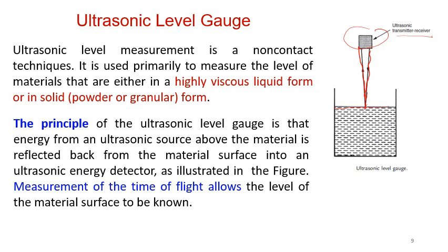The simple way of analysis is just to measure the time taken by the signal from when it left the transmitter until it comes back to the receiver. I mean the time taken for the signal to start from here, go to the surface and come back. It's going to be different if the water level or the level of the liquid is at this point or at this point.